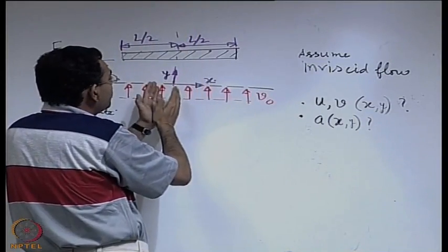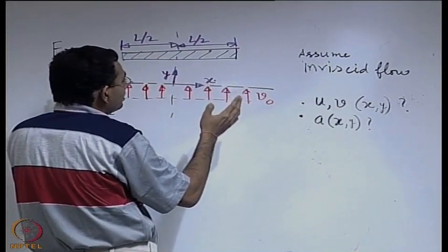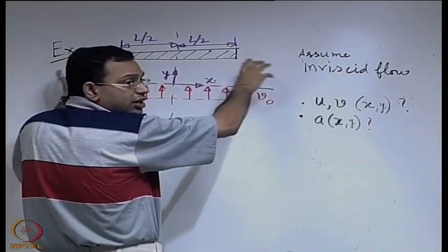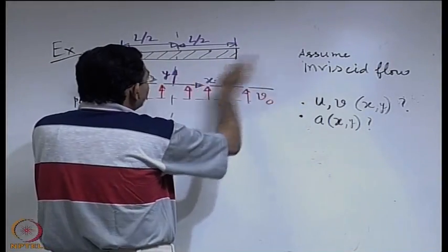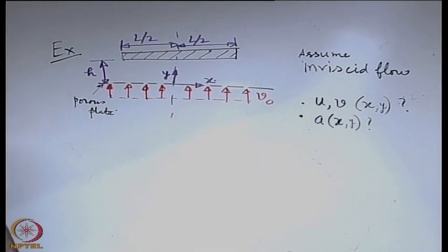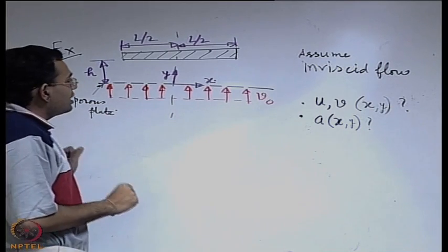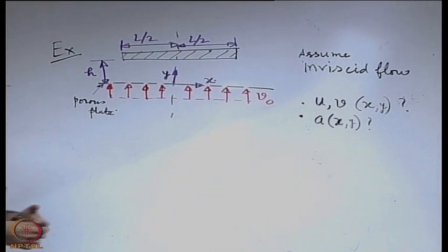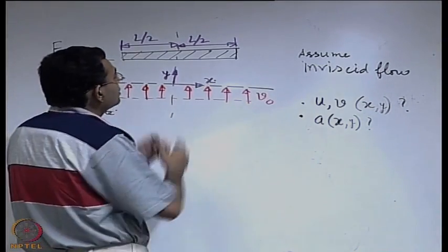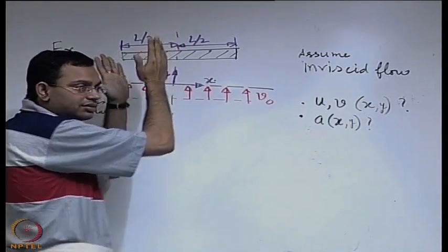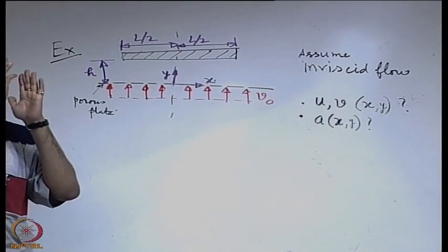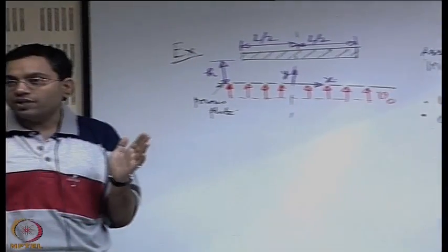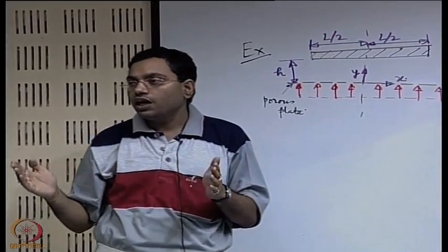So the only way this fluid can move in a steady condition is it can move sideways. So whatever fluid enters, now maybe half enters right and half enters the left. Okay. So what we can say is that we may write a gross overall mass balance. When you write a gross overall mass balance, what we have to keep in mind is that very simple equation, just like rho i into Ai into ui average is equal to rho e into Ae into ue average.